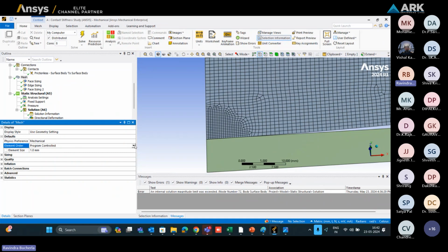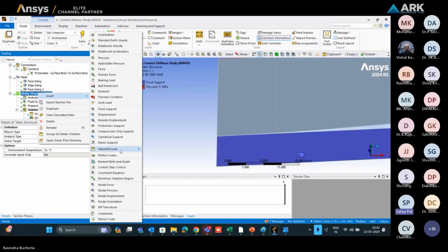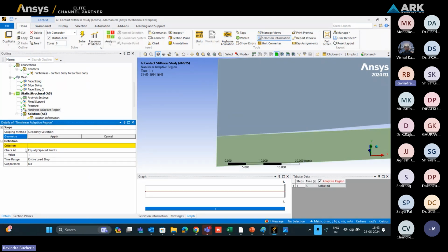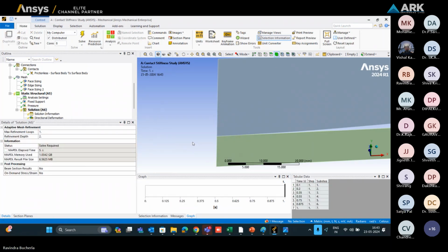Also you can try element order linear. We generally face this kind of highly nonlinear issue with hyperelastic material, so you can try nonlinear mesh adaptivity. There, if you are using tetrahedrons or any other element, you can provide the value there, the criteria to avoid the distortion. Okay.